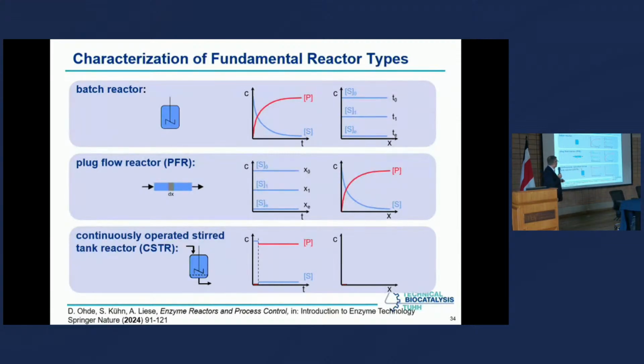The big difference between those two is that in the continuous stirred tank reactor, we operate the whole time under maximum concentration of the product. What we measure at the outlet, we will find all the time at every point in the reactor, and that is true for time and for space. So we're always operating in the reactor at minimum starting material concentration and maximum product concentration. Sounds simple, but it has humongous effects if we're thinking about taking a reaction running in here to continuous operation.